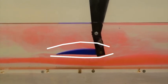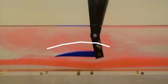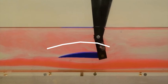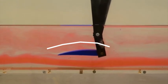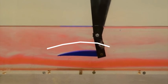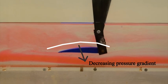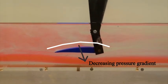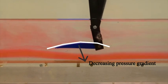A proper understanding of streamlines can be useful in fluid mechanics. Besides velocity, pressure can be measured through the curvature of the streamlines. The center of curvature points in the direction of decreasing radial pressure. A relationship between pressure and velocity can then be derived from Bernoulli's principle for a location along a streamline.